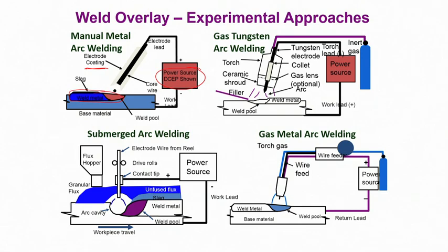This is the weld overlay that you form, and as you move, you can cover a much wider surface area. Here, the electrode also gets consumed in the process to some extent. On the other hand, if you use a tungsten arc welding process, the tungsten wire is a non-consumable electrode. Essentially it is the same process, the same kind of configuration. The difference here is that you create a much higher energy arc. The temperature here could be even higher, but you feed in a filler wire here.